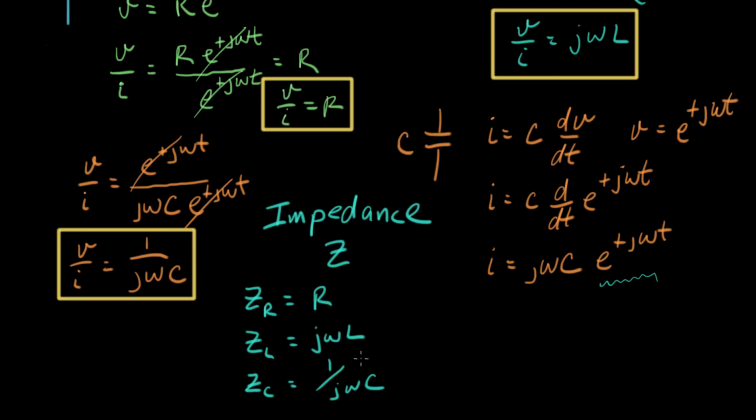So it's somewhat of a notational trick. We associate this frequency dependence not with the inputs and the voltages and currents, but with the components themselves. And this is referred to as transforming. We've transformed our components. That's the phrase that's used there. But from this comes the idea of impedance, in the general sense of the voltage to current ratio.